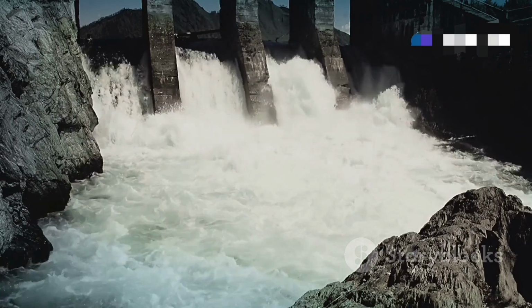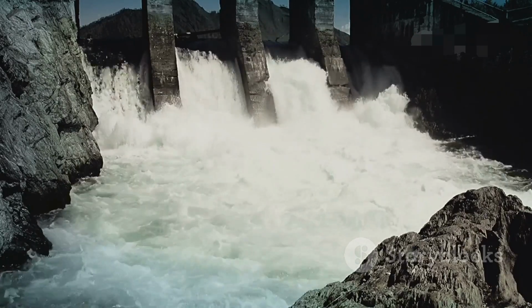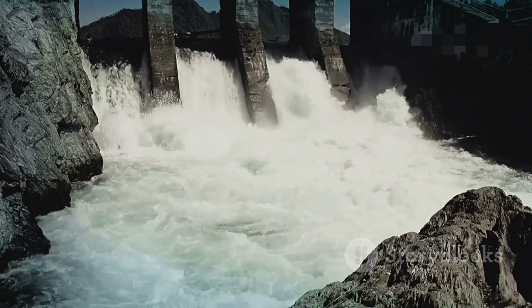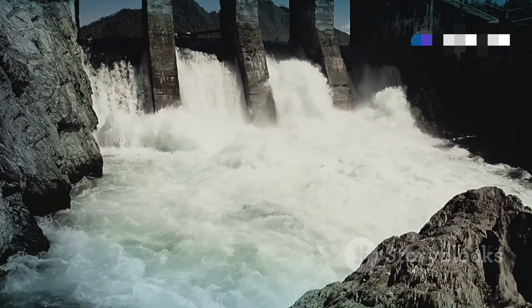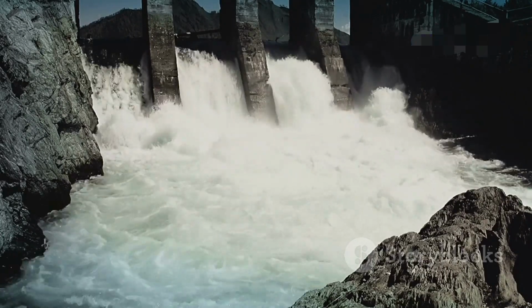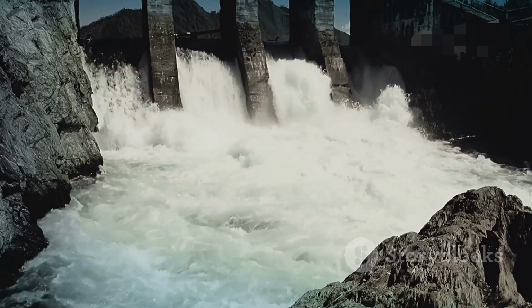The side slopes of the breach describe how steep the sides of the opening are. This is usually expressed as a ratio, such as 1 vertical unit to x horizontal units, 1V:xH. For earthen dams, the side slopes depend on the stability of the soil material forming the sides of the breach. Cohesive soils might stand on steeper slopes, while sandy soils will form flatter slopes.